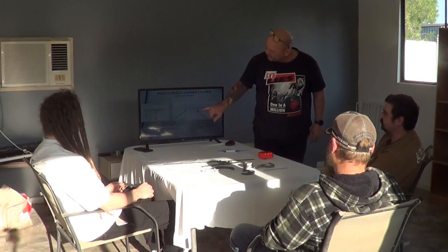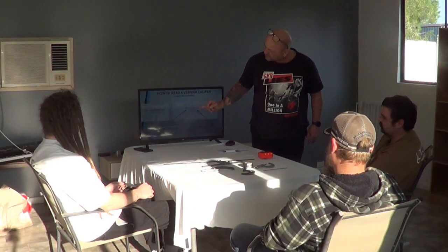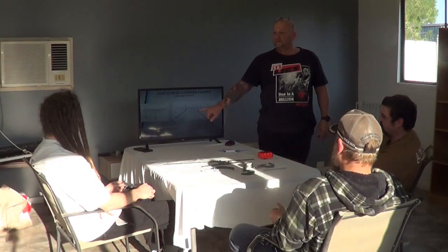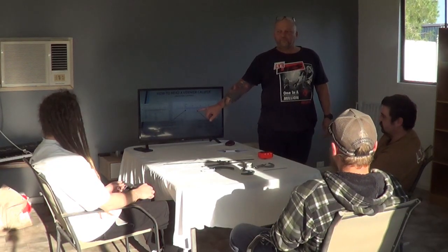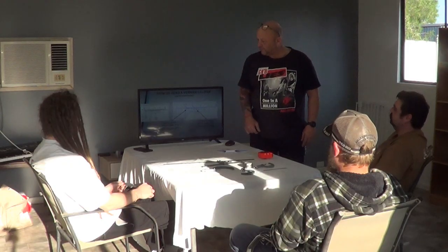Then you look at where your vernier scale lines up. That line does not line up with anything, that almost lines up. You see how that one lines up with another one? That gives you your decimal reading. Make sense? Yeah. Cool.